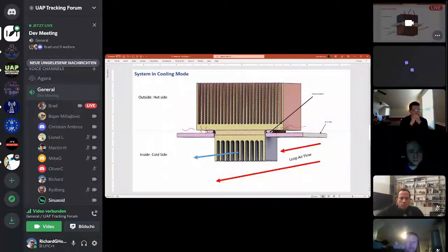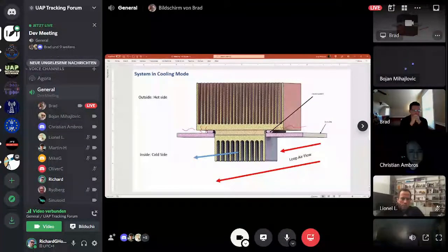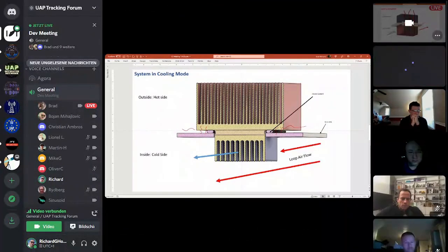Yeah, absolutely. Inside of the cooling enclosure, we actually have 4 peltiers. I mean, the prototype will start with 4 peltiers. Maybe we end up with 2 peltiers. And from my analysis of the airflow, it makes sense that the peltiers that are in serial, so after each other, are set apart a little bit, so that the air is not going through both of the heat sinks. The second heat sink is, let's say, 2 millimeters off of the axis, so that the air is very turbulent when touching the heat sinks and not flowing laminarly through.